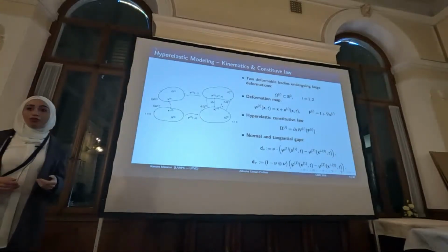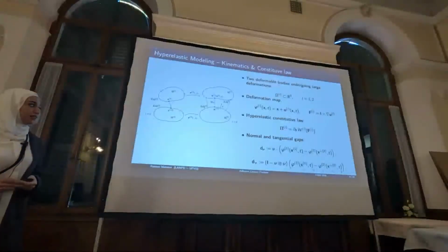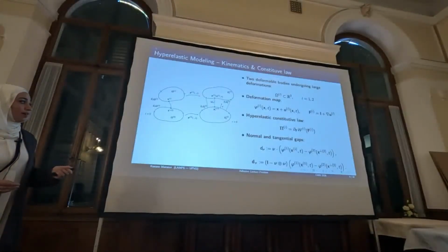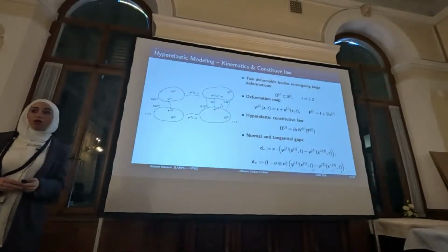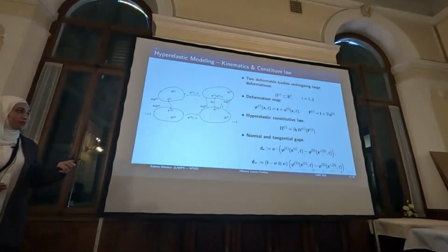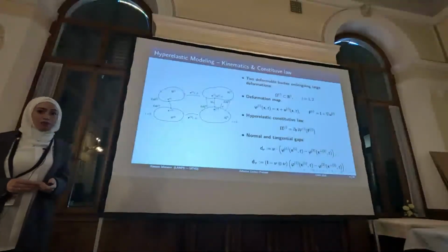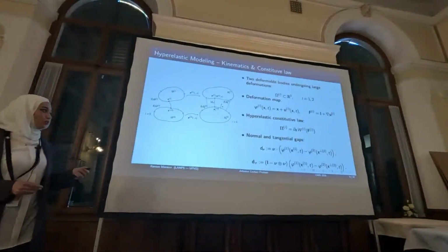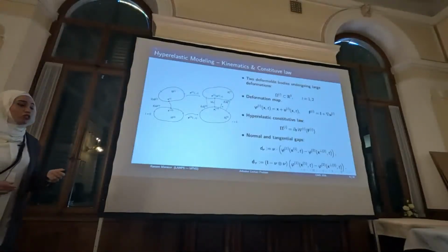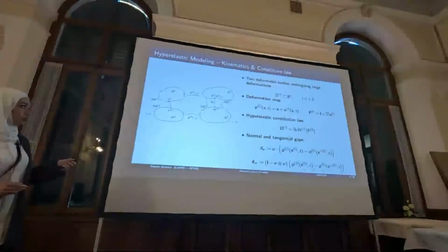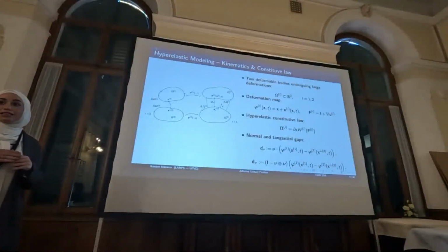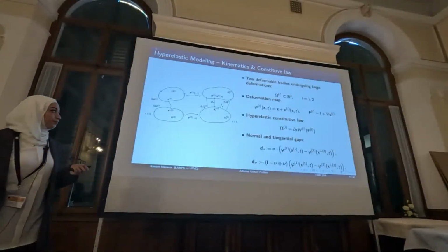The physical behavior of each body is hyperelastic. It's fully defined by a strain energy density W, where P represents the first Piola-Kirchhoff stress tensor and F represents the deformation gradient. To describe the interaction between two reference bodies, we introduce the normal gap, d nu, which measures the separation between two bodies, and the tangential slip, d tau, which represents the displacement in the tangent plane.